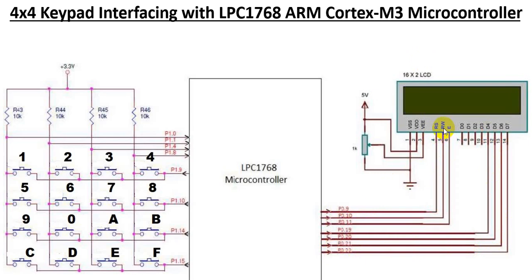Then comes the read-write signal. So read is to read from the LCD. Basically, we read whether the LCD is busy or not, but we are not using this functionality here. Then the other option is we can write. So we are not reading here, but we are writing here. In order to write, this R/W bar should be equal to 0. Then you can write to the LCD. You can write a command or you can write even data.